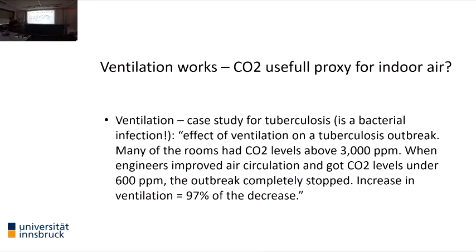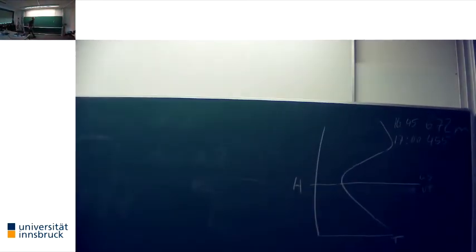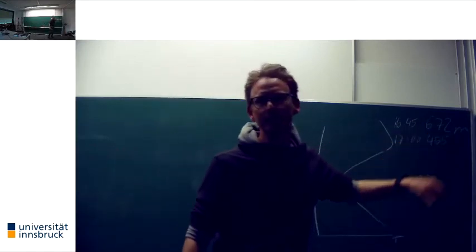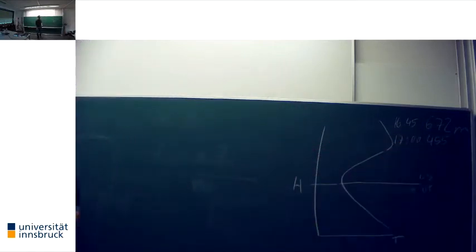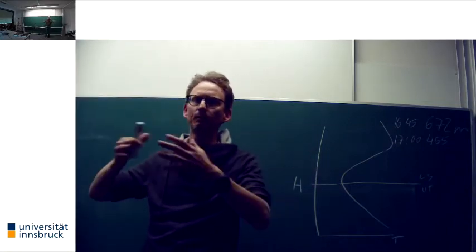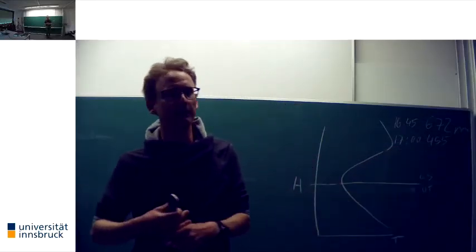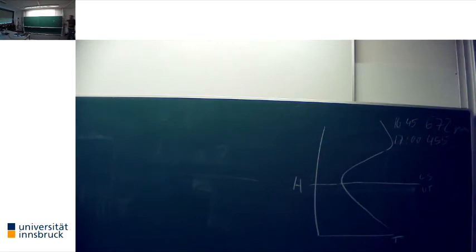This is also something that people on the stream cannot really follow closely, but let's see if I can just turn on the light here. We have a CO2 sensor here, and when we look at where we started before we left for the break, we had a CO2 concentration of 672 ppm. So I would say this is still acceptable. Then we opened the door and opened the windows especially. It dropped quite fast to 455 ppm. Outside concentrations are typically in the range of 400 ppm, so this is a really acceptable level.